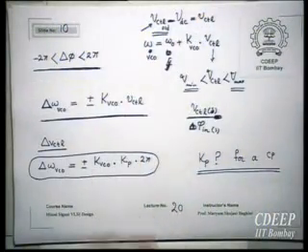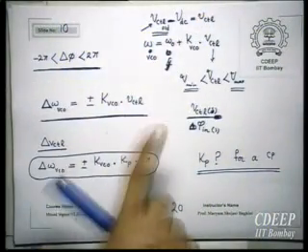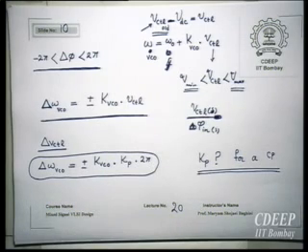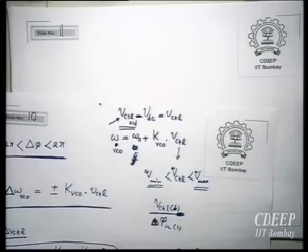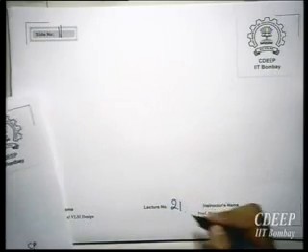Now the question is, what is capture range? So here I had assumed that VCO is working properly, it will be changing its frequency with the VCTL. But when loop is not locked, VCO doesn't operate in this way. What VCO does? VCO is operating at its free running frequency on average. Now, how can we estimate? So now this is just an estimation, and then it will give one idea of what will be the capture range.